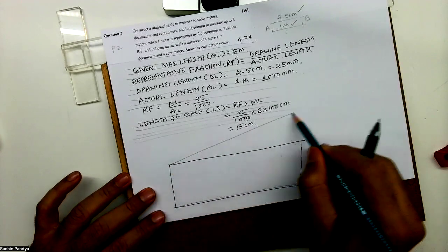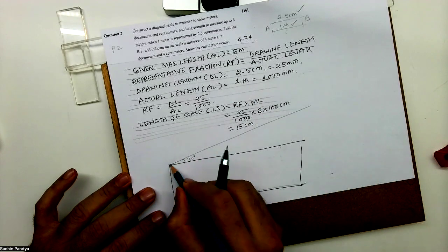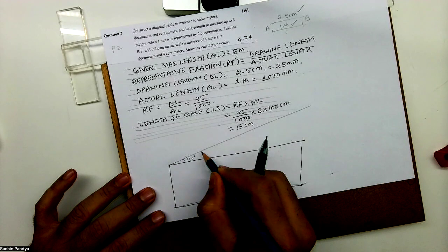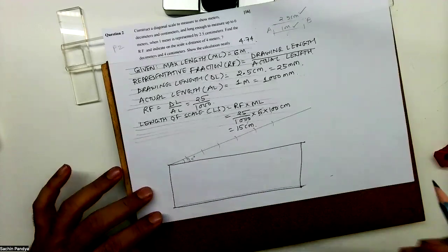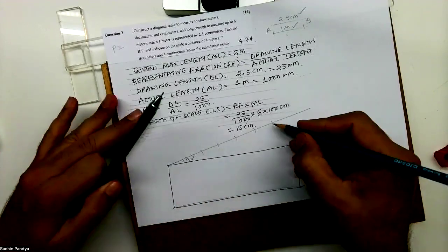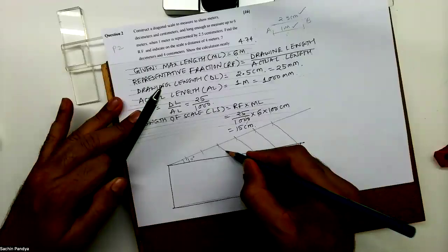So I will draw angle. See, this angle we generally take 30 and the second angle we take 45. Again on this you take 2 centimeter. 1, 2, 3, 4, 5, 6. And join this to this and draw with the parallel set square you can draw parallel line.